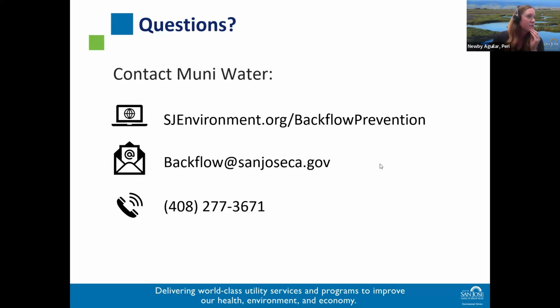We have another question here. The landscape installer for my then new house didn't even mention a backflow prevention device. He needs to be educated. Well, someone else also mentioned that this is the first time he or she has heard of this program. So it could be that a lot of this is already installed. It just goes unnoticed. There are requirements for hoses sold at hardware stores to have a vacuum breaker already installed. So you would have to intentionally take that off your hose to not have it.